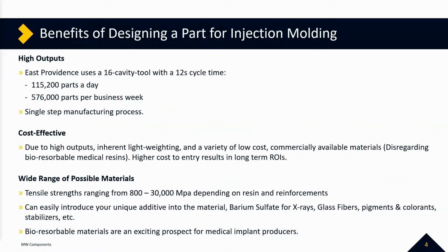So what are the benefits of designing a part for injection molding? Why would you go with injection molding? Well, first and foremost, really high outputs. As I said before, it's just a single step process in which an entire part is formed all at once. By adjusting for cavitation, wall thickness, which we'll get into, you can start to hit really high throughputs.